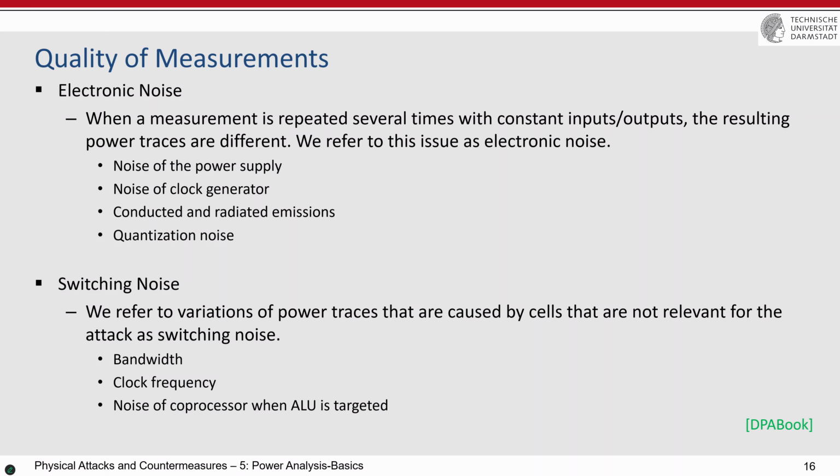For example, you are interested in just what we learned in the timing attacks, the MSB of the SBOX output. You want to make the attack on just that, and we will learn later the dependency of the power consumption on the MSB of one of the SBOX outputs, but the SBOX has other outputs as well, and each of them also affects the amount of power consumption.